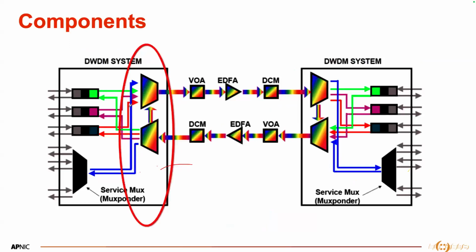But you have to make sure that the loss or the TX power which is needed for the system is maintained by that client device with color optics. Are you getting the point? Maybe in your DWDM system, you have OTU cards which have a launching power of minus 2 dB. And now you are connecting with a client.